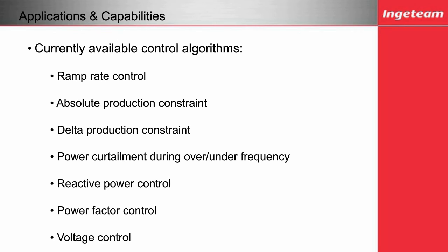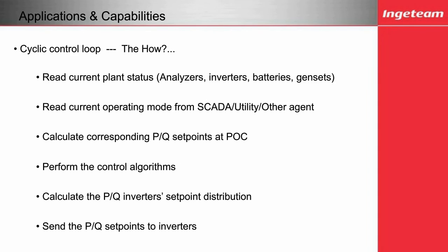Voltage control, reactive and active power controls, and power factor controls to help stabilize the grid operator are additional controls that you gain by implementing a plant controller on the entire system. How our plant controller takes into account the status and the modification of the entire array: the plant controller at the point of interconnect is continuously measuring the status of the system.